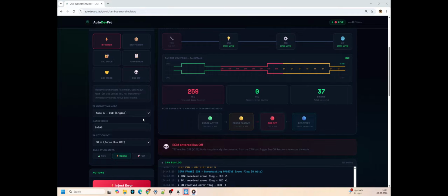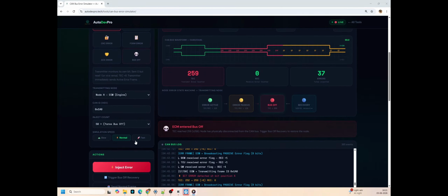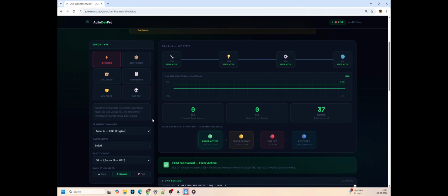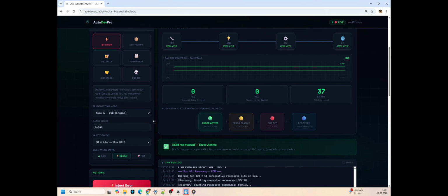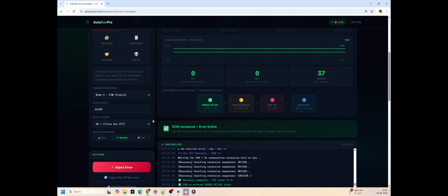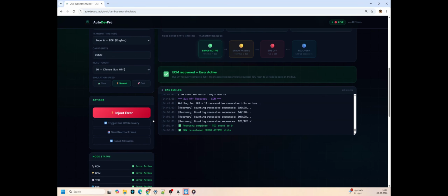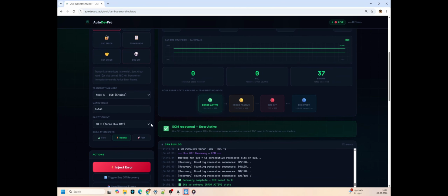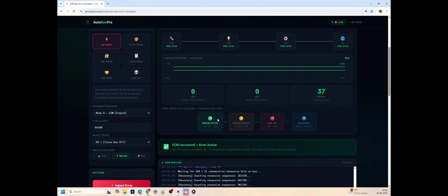Now, let's see bus off recovery. A bus off node waits for 128 sequences of 11 consecutive recessive bits. Why 11? Because a complete CAN frame with interframe spacing has at least 11 recessive bits. Waiting for 128 of these sequences means the node waits for approximately 128 successful frame transmissions on the bus before attempting to reconnect. This guarantees the bus is stable and healthy before the recovering node re-enters it.